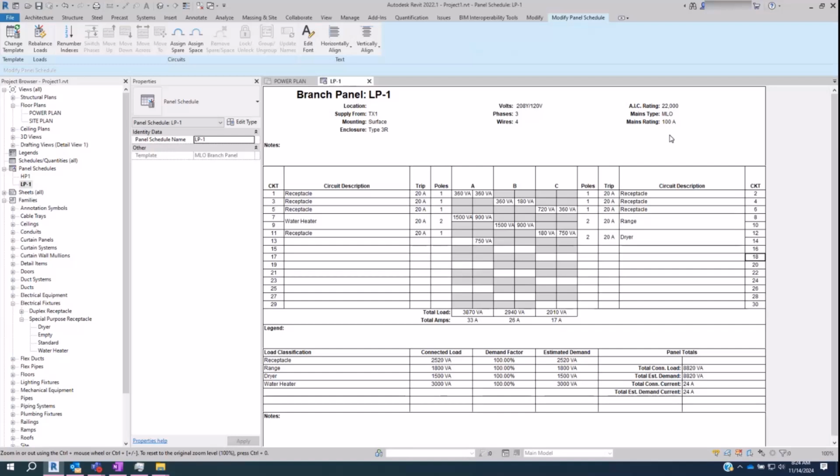It's already there. However, if you have only the breakers that you need in there and nothing else but spaces, and something does come up that they need to put in there because the client requested it, they're going to push a change order through and charge the client $3,000 for a $10 breaker because it's a change order. So yes, leave spaces and spares both in most panel schedules most of the time.